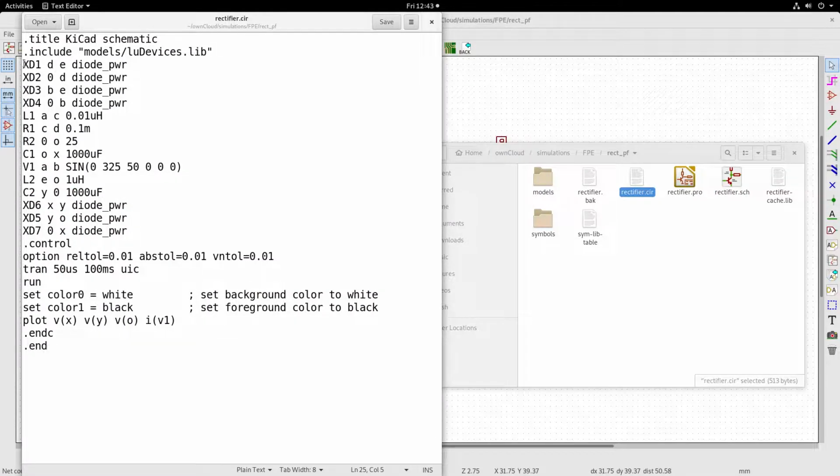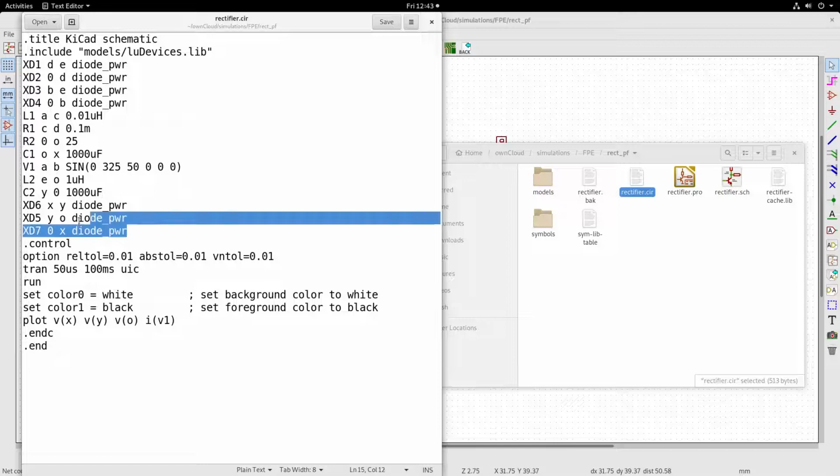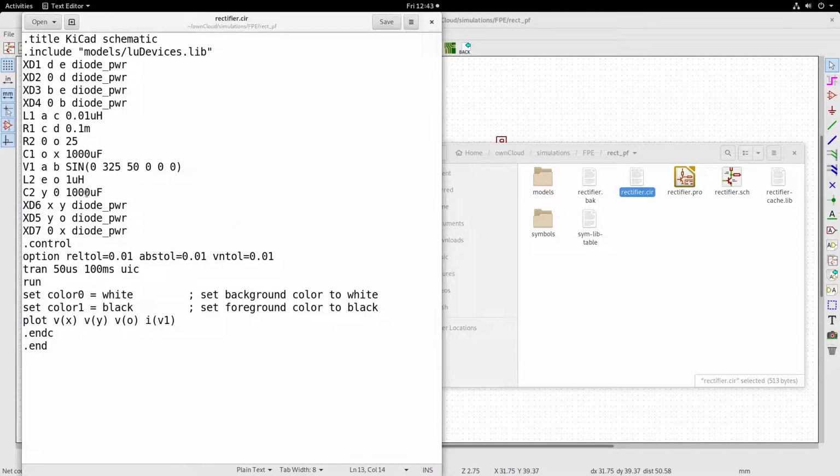So you see the entire schematic. This is basically the full bridge rectifier part, and you see these diodes are the passive power factor improvement part, and you have C1 and C2 coming in here. And let us see the voltages Vx, Vy, and see if they are as per the discussion that we did during the theory classes.